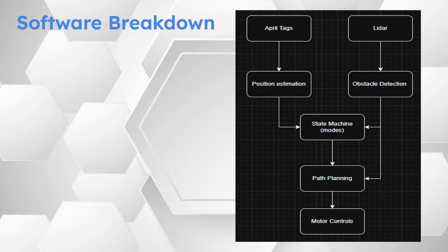It's a rotating LiDAR that we're going to put in the front of the robot. That will hopefully be able to detect both rocks in the way as well as craters. We are very confident that we can have it detect rocks. Craters are a little harder to detect, being that they're in the ground, but we have a possible solution involving angling the LiDAR, but we need to do more testing on that before we verify.